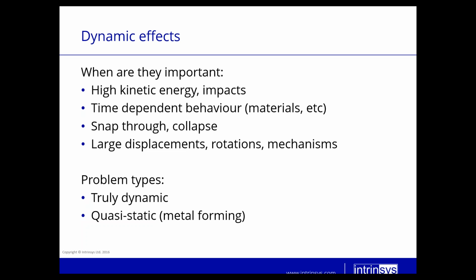Then you must simulate your structure in the time domain. You can have snap-through or collapse type behavior, which again, you might be able to simulate with a static procedure, but a dynamic procedure definitely handles it. Also, if you have very large displacements, large rotations, or other mechanisms in your model, then dynamic simulation is probably the way to go forward.